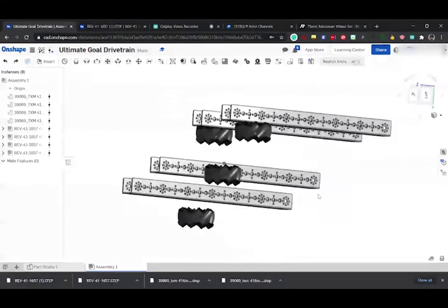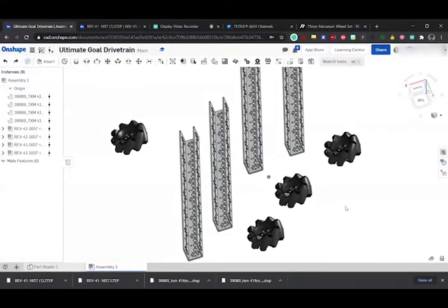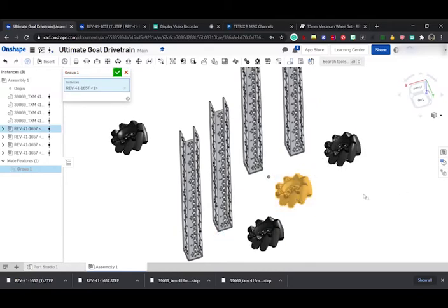So the solution to this is you get out the group tool, you press and hold on a spot where you can drag the box, kind of similar if you played on a Windows desktop where you can drag and bring out the mouse and it'll create a box. We can do the same thing in CAD where we want to highlight the whole thing with the dragging box, and once we know that we've gotten the whole thing in the box, we can select group. Now, when we try and move the mechanism wheel, it moves as a whole, which is what we want.